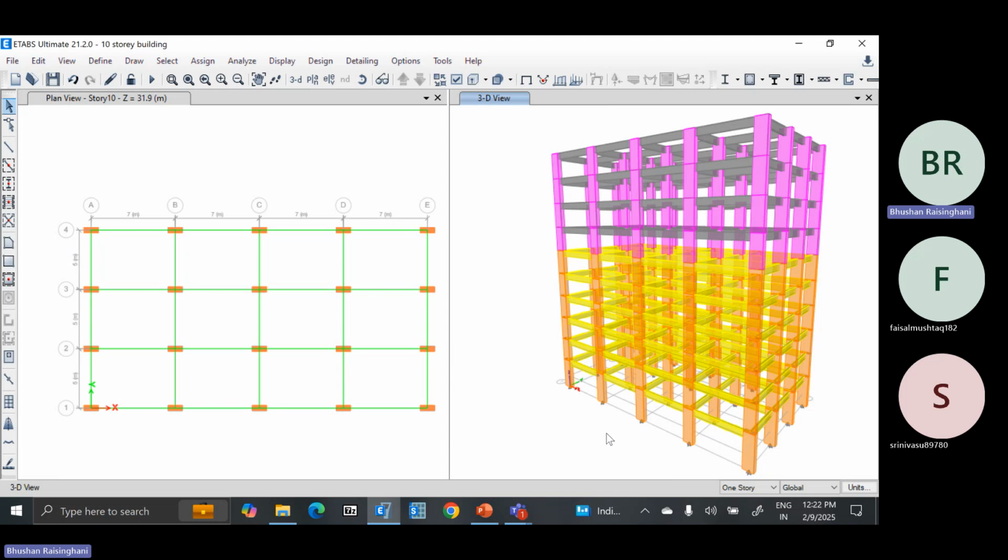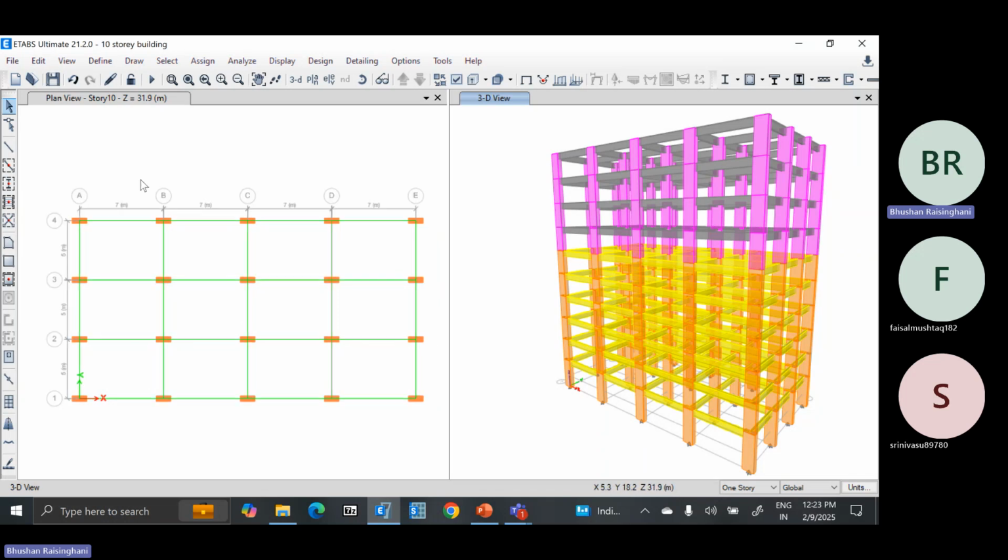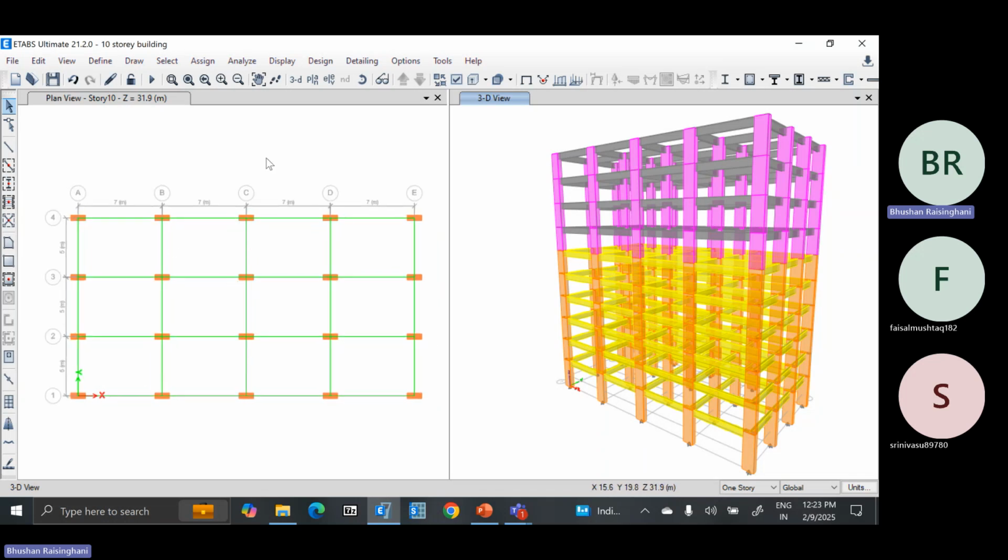So as I chose for the section properties differently, so this many floors are C1, this many floors are C2. So this also used to check whether you have modeled it correctly or not correctly. So up to 6 stories, the beam colors are different. B1 and B2 are also different. That is clearly visible on this arrangement. And here the different color is available, which I had chosen for column and beams. So this way you can create different things to check your modeling.